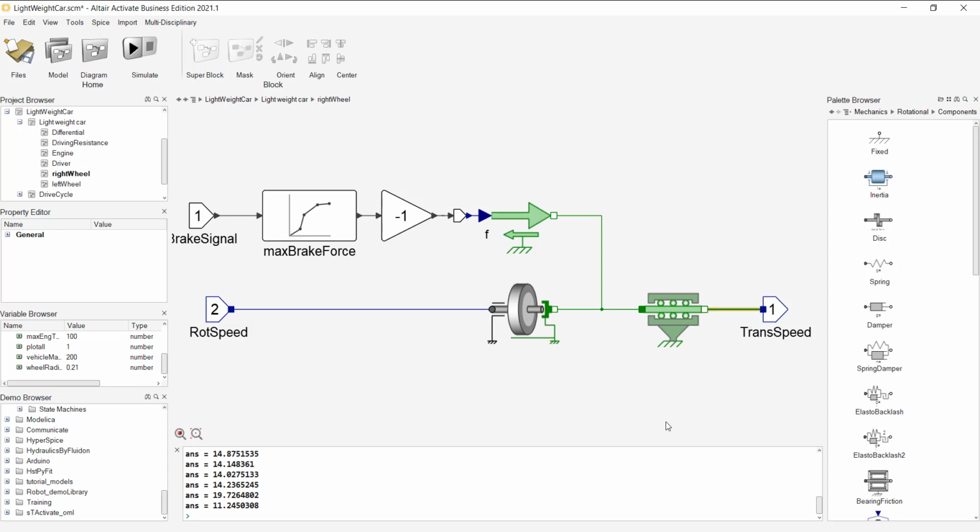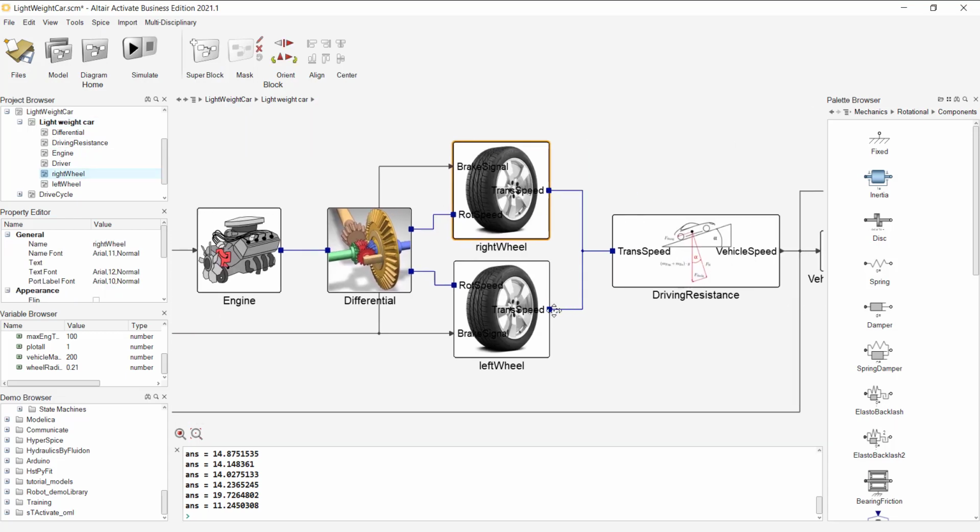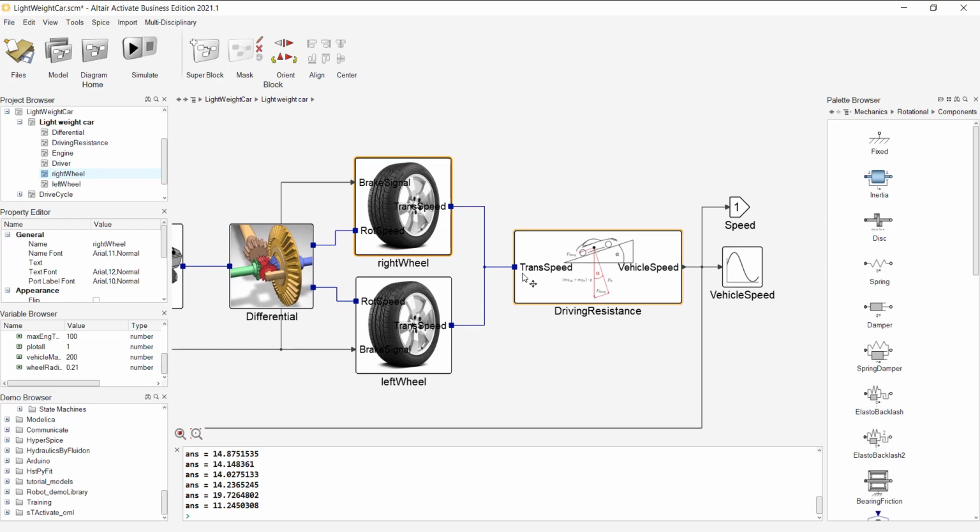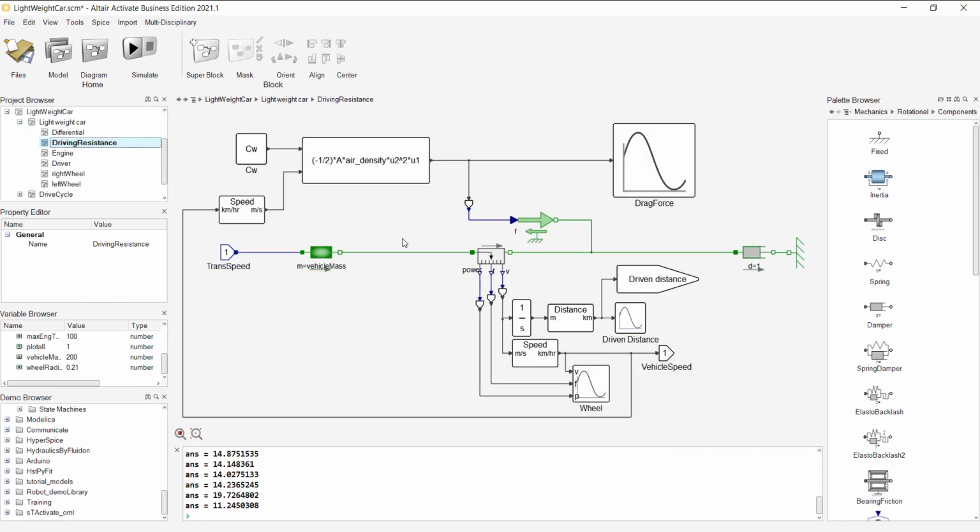Okay, so now we can measure our forward speed of the vehicle, which is a summation, the forward speed taking into consideration friction and our brake force here. So you see how we're adding together, we're compiling sort of our vehicle dynamics, our set of four states that we saw in the previous slide. So now moving to the right in our system diagram, we have our driving resistance, or our drag force.